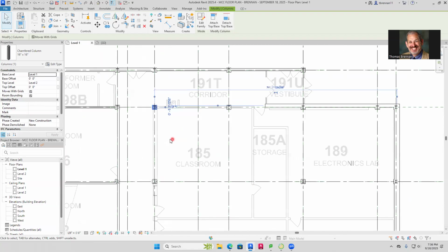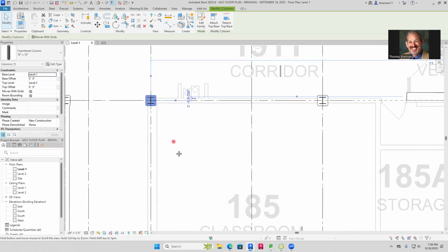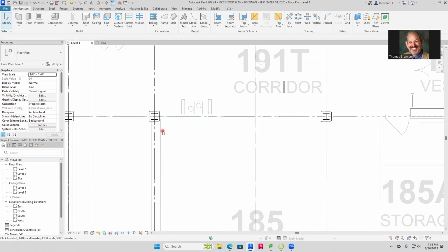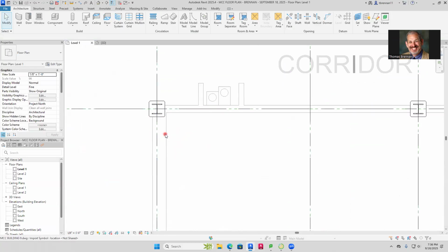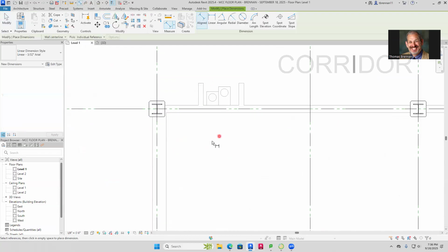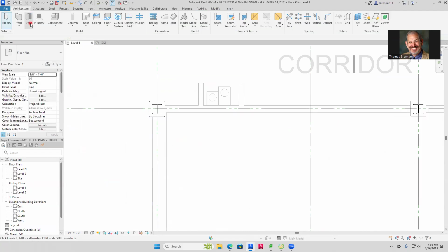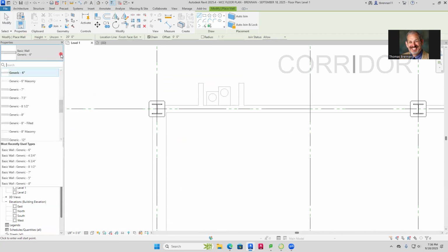Now, when you go here, it looks like this. I have some walls. I've got a wall here and a wall here. I'll measure this one first. I see that the size of this one is 1'2". I don't think I have a 1'2" wall. So I'll start with a wall here, and it doesn't matter which one because I'm going to make it a different size. For this one, I'll just make it generic 1 foot.